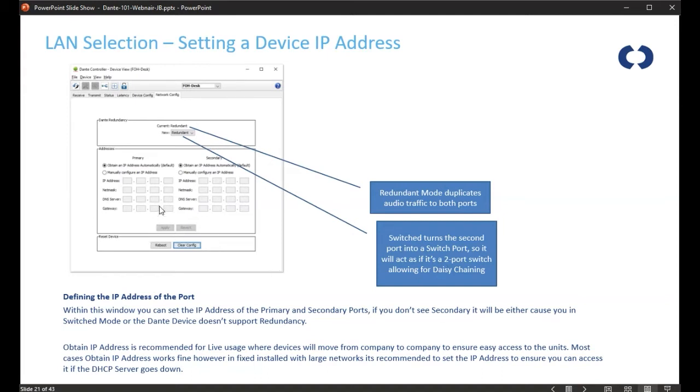What that means is if you have one DSP and then another DSP, and you connect Dante between the two of them directly, no switch, then it will obviously work. But how am I ever going to do the routing if I've got one direct connection and no switch? Well, if you're in the switched mode, you can plug into the second port and that'll allow you to access everything on that. It creates a daisy chain, so it'll allow you to see the other device through that. Switched mode is useful for live applications where you have stage box to console and you want to access the other side of it. Or more importantly, if you have other situations where you just don't have a switch and you want to create it a little bit reliable, it's good to know.